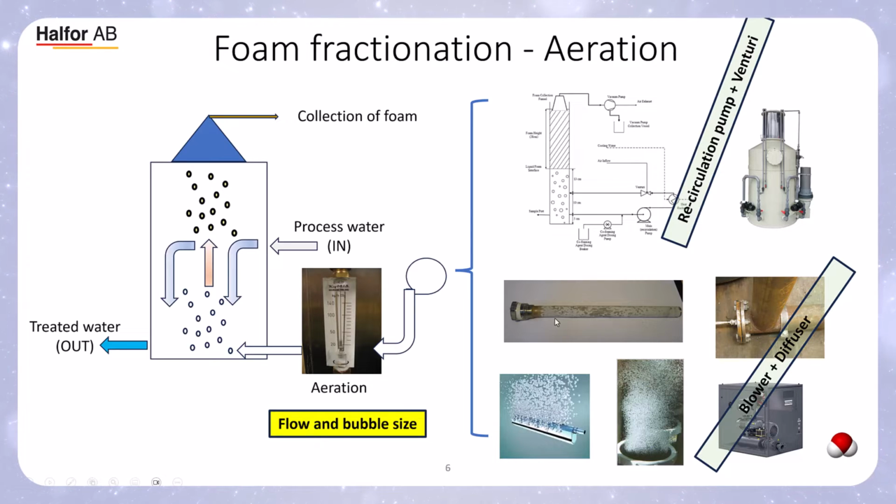So here you get very fine bubbles, and here you see an example of a sparger I've used, not for PFAS removal, but actually for dosing carbon dioxide. Here you have very fine bubbles from this type of sparger. But again, you have to look at how big the reactor vessel is, and whether this is a practical way of introducing the air.